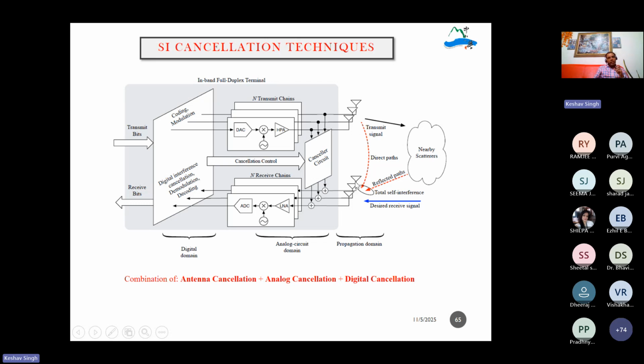From here we can define the antenna correlation factor, and then we can pair the antennas with the lowest correlation factor, through some DNN or some mechanism to find the antenna correlation factor, and that will reduce the self interference impact. If they are highly correlated, interference will be very high. If less, then self interference will be very low.